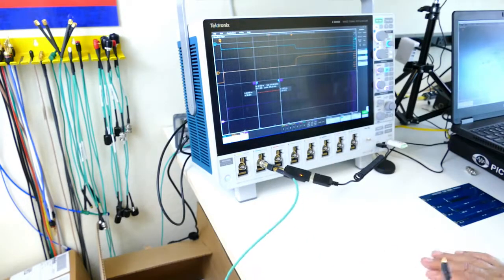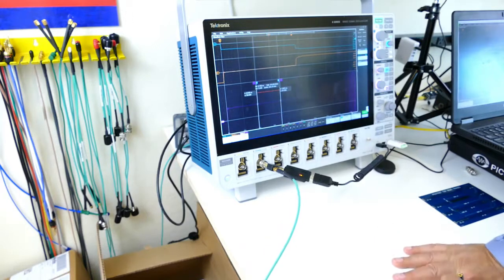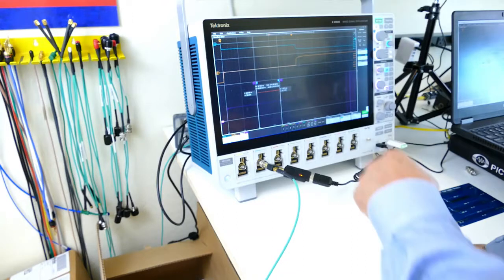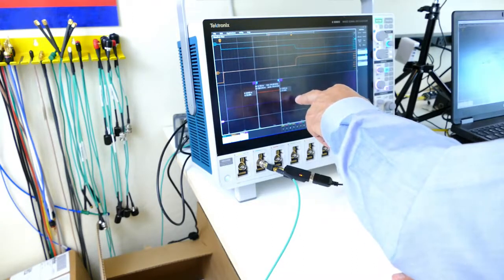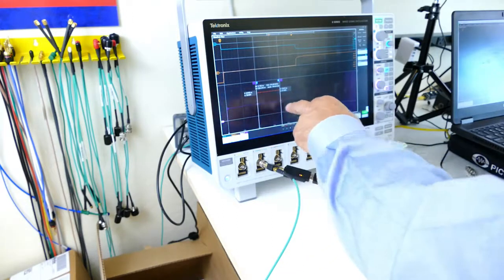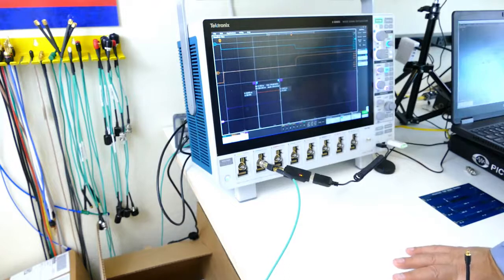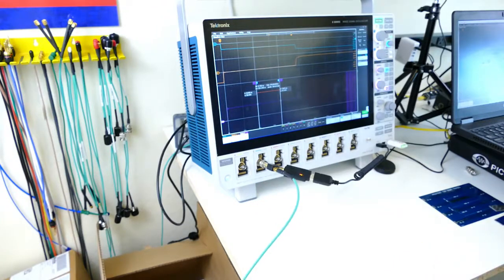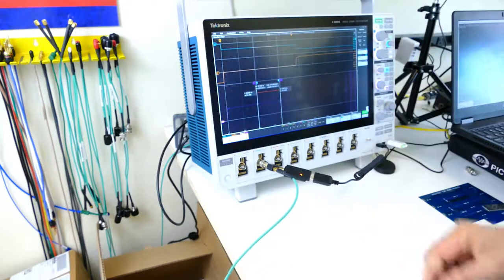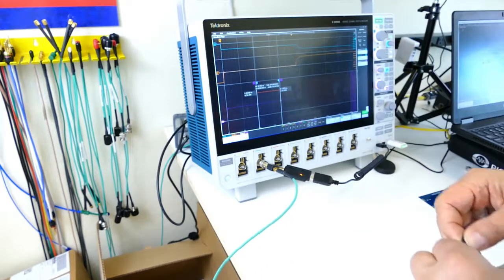And it's a good idea to check your cables, because we want to make sure that the cable's in good shape before we make measurements. If it's not, usually what we'll see is degradation in these impedance measurements at one edge or the other of the cable, and that's a reflection of how good the crimp is. And once we have the cable, we can also connect it to a probe, which makes it really handy.